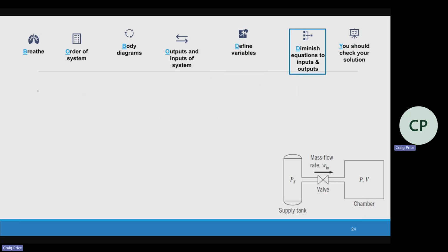Okay, so first condition is choked. My capacitance I can rewrite as V over nRT times pressure drop. This is equal to M in dot, the mass flow rate coming in. If it is choked, that equation, which I showed a while ago, is equal to this.